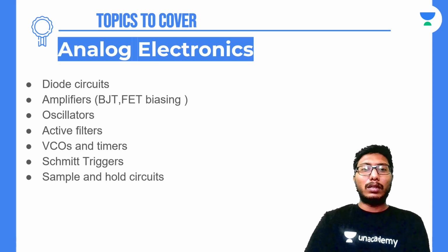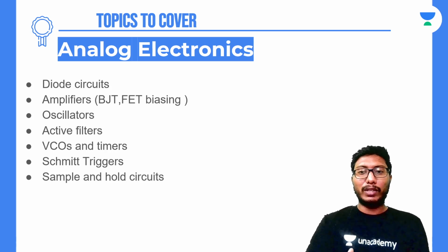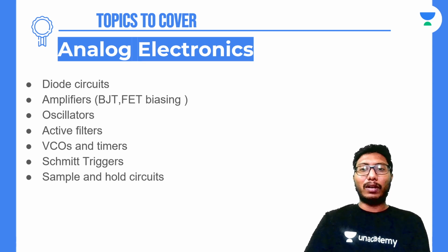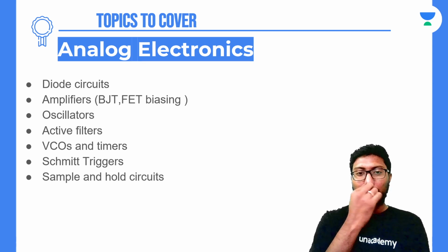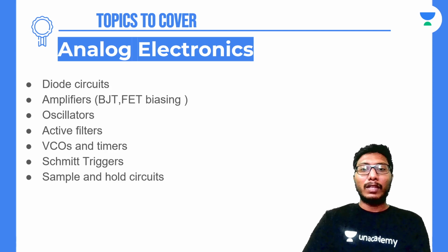So as I told you earlier, basic thing is, first you have to do DC analysis. From the DC analysis, you will find out the operating points. From the operating points, that is from operating current and operating voltage, you will calculate transconductance and R naught, and from these two you will be calculating the gains. The same method you will follow for every problem of FET amplifiers.